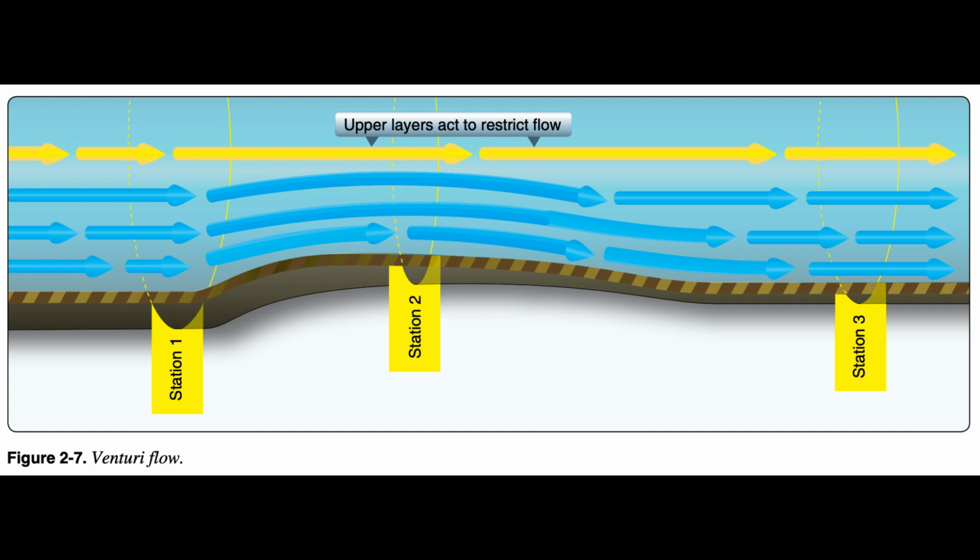Fluid flow pressure has two components, static and dynamic pressure. Static pressure is the pressure component measured in the flow but not moving with the flow as pressure is measured. Static pressure is also known as the force per unit area acting on a surface. Dynamic pressure of flow is that component existing as a result of movement of the air. The sum of these two pressures is total pressure.